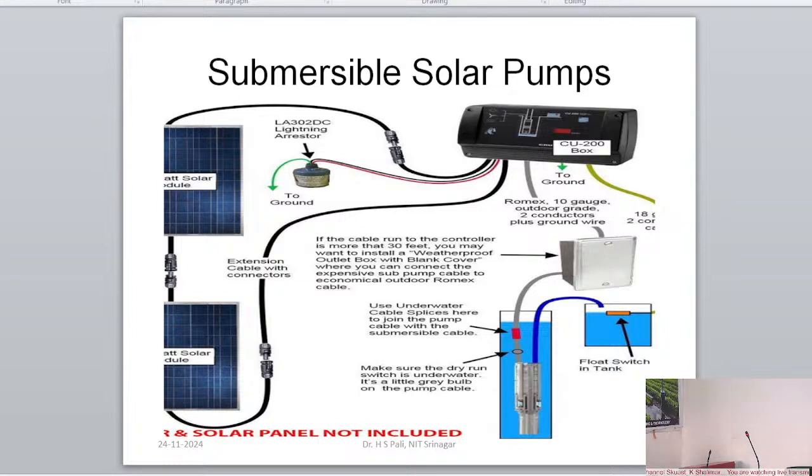Recently, submersible pumps have gained good market shares in both the industrial and domestic sectors due to their high versatility and reliability. They need no priming, they are not prone to the issue of cavitation, and are very efficient. The submersible pump is a centrifugal pump.